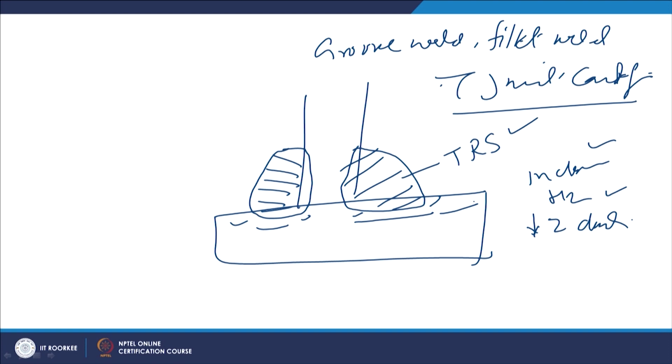So, what we basically have to do for controlling lamellar tearing is change or shift the location of the weld suitably. Instead of having the fillet weld, we can redesign the components so that we have the butt joint configuration. Simply shift the location of the weld so that the residual stresses are redistributed in a more favorable manner, in order to avoid such cracking tendency.